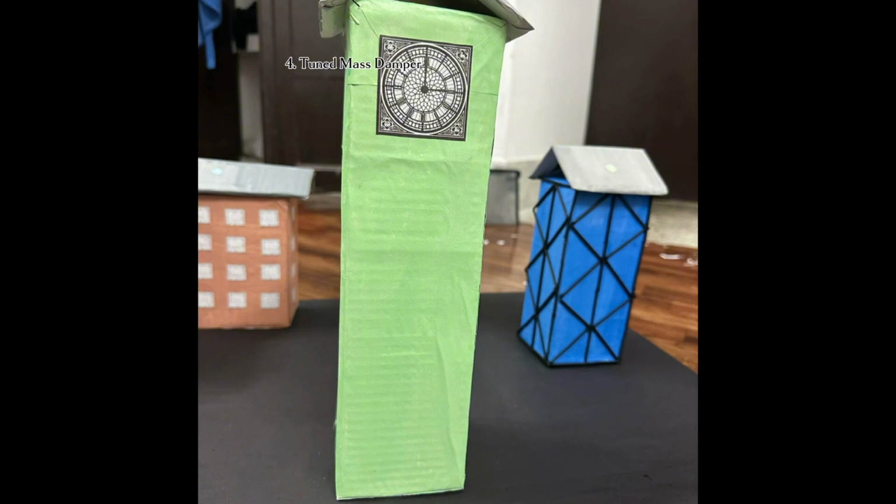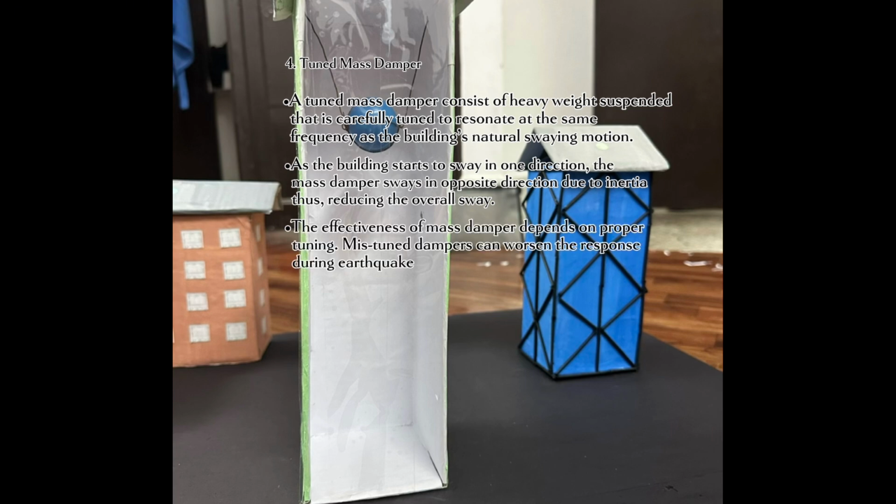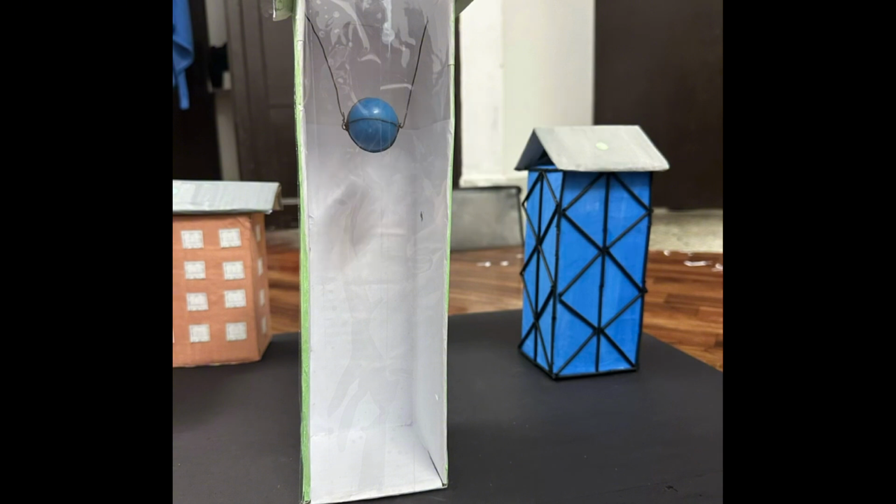4. Tuned mass damper. A tuned mass damper consists of a heavy weight suspended that is carefully tuned to resonate at the same frequency as the building's natural swaying motion. As the building starts to sway in one direction, the mass damper sways in the opposite direction due to inertia, thus reducing the overall sway. The effectiveness of the mass damper depends on proper tuning. Mistuned dampers can worsen the response during earthquake.